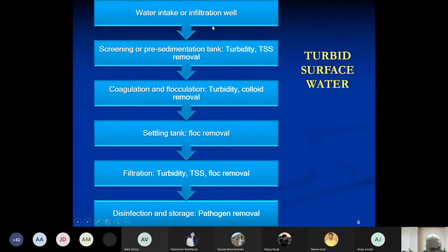In Kharagpur city, not in the campus, but in the city, they have what is called an infiltration well. This is a river infiltration well where there are horizontal pipes. They may be either above the riverbed or below the riverbed. They're perforated pipes. They take in water from the river, or in some cases it is filtered through the riverbed.